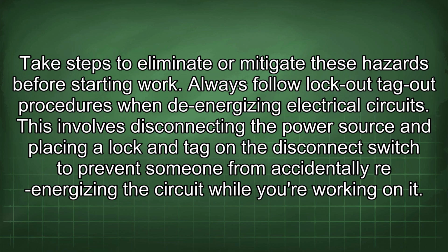Always follow lockout-tagout procedures when energizing electrical circuits. This involves disconnecting the power source and placing a lock and tag on the disconnect switch to prevent someone from accidentally re-energizing the circuit while you're working on it.